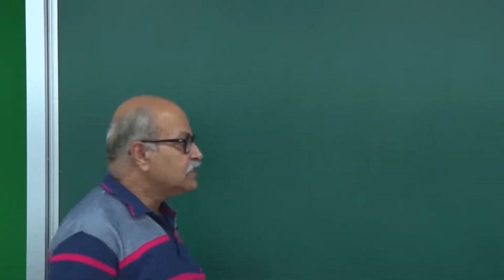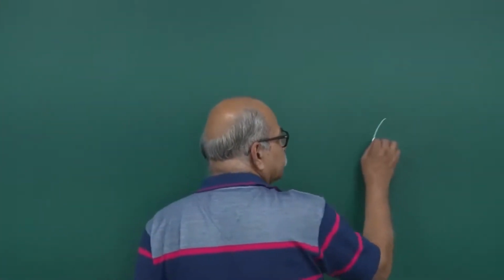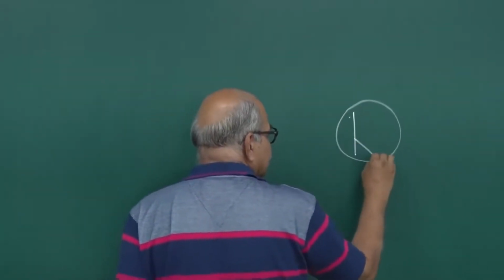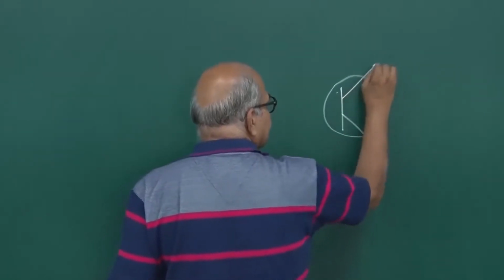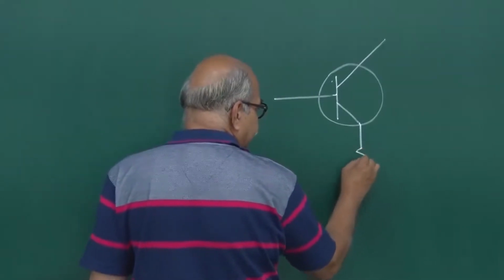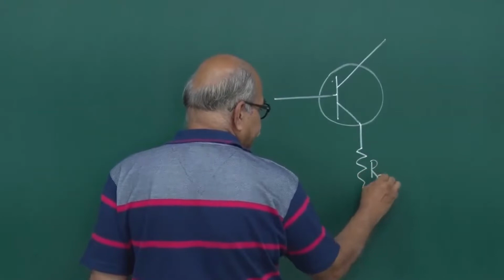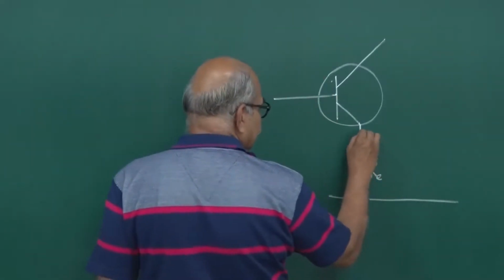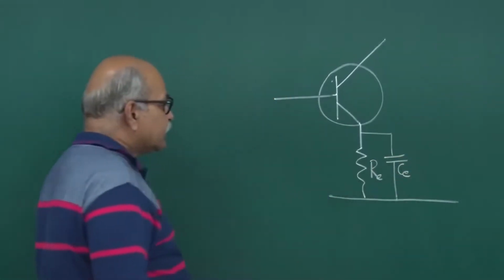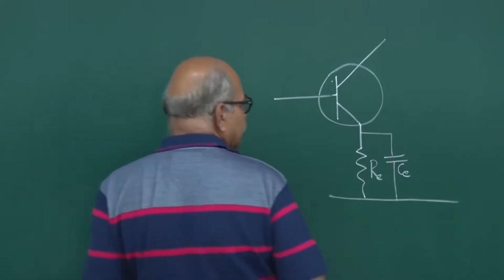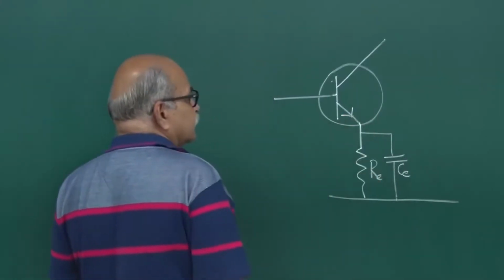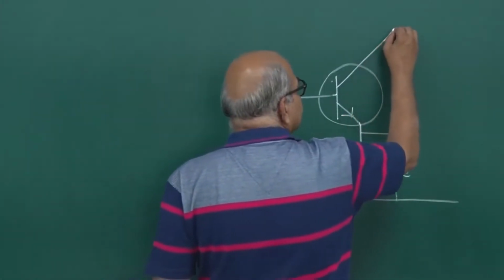So, in a transistor amplifier in common emitter configuration, you have this emitter here and collector here, base here. Then you put this to ground, some resistance. In actual case you also put some capacitor, so that this alternating thing is bypassed from here. And then this side should be forward biased, and this is an NPN transistor, so this should be forward biased.